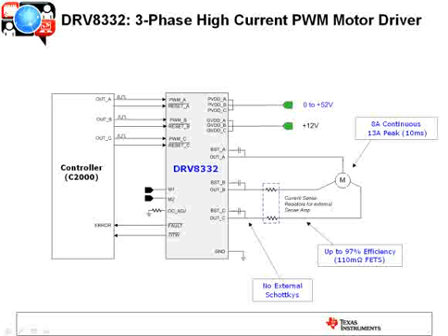And you need to be careful, make sure that you're not just reading the peak current, you need to look at the continuous current. The peak is exactly that. It's meant to, the device can withstand that level of current for very short intervals, say, on the milliseconds or microseconds, just depending upon the device. That could be your peak currents during startup or stall and so forth. But continuous, 8 amps continuous, these are very efficient devices, up to 97% efficient.